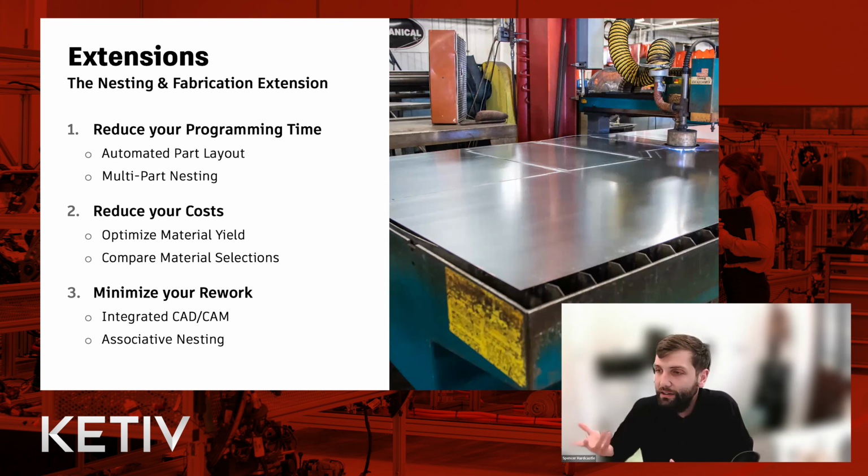Reducing cost. At the end of the day, it's all about cost, money, money, money. And when we were talking about reducing costs, it's all about optimizing your material yield. So bringing in those external components, thinking about orientation of parts and flexibility of orientation too, thinking about grain control, comparing different material selections. We all know that sheets of aluminum or aluminium, of course, depending on where you are, come in different shapes and different sizes. Same for steel, same for any sheet stock.